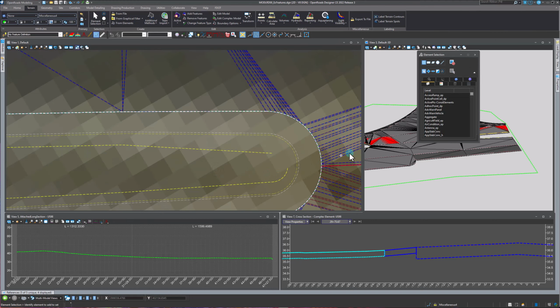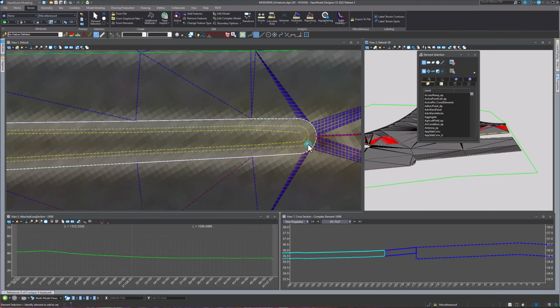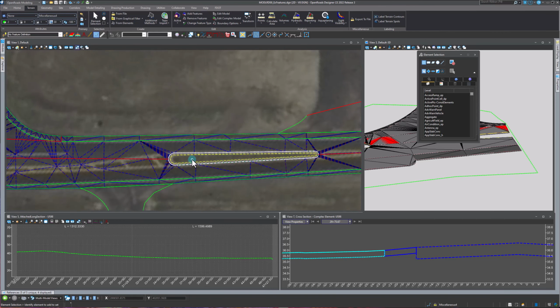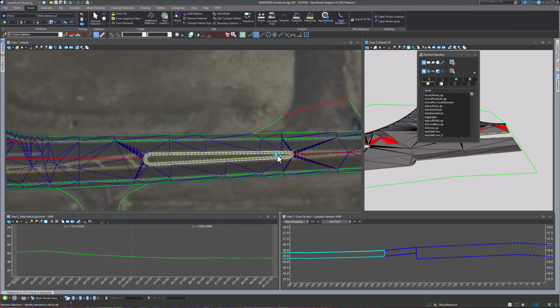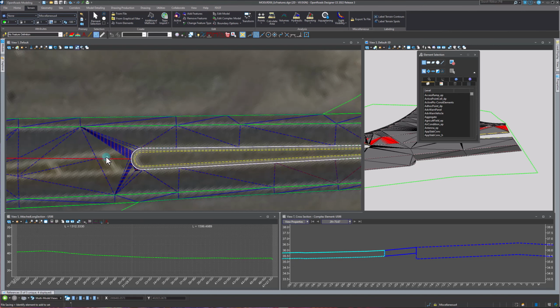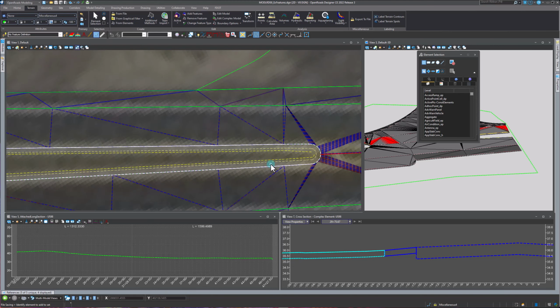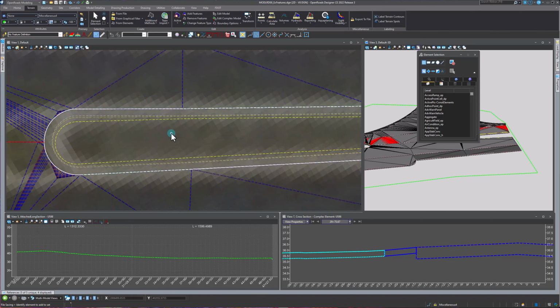Okay. And what we need to do is, this curb gets a little bit tricky, because ultimately what we want to do here is either put a linear template or a corridor on here. We're probably going to just do a linear template, because we don't need all of the extra features that a corridor allows us to have. Linear template's much simpler.